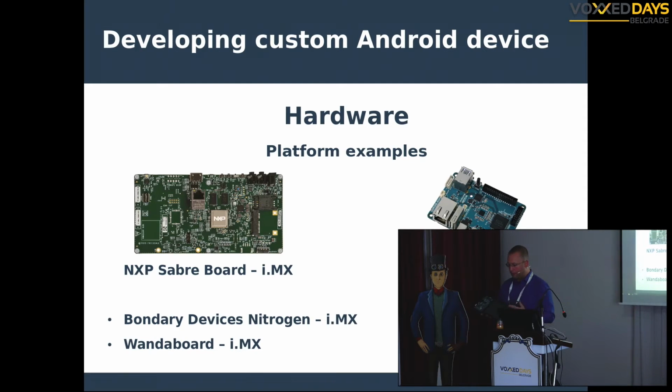It has audio, it has buttons. So on a development board you usually have a lot of peripherals, and you will probably be able to do everything on the development board that you want. If not, there are always some expansion ports, protocols, which you can connect your custom thing. In our case, we were building a remote that I will show you later, and it needs infrared diodes. So here you do not have infrared diodes, but you can plug them in easily and get them working.